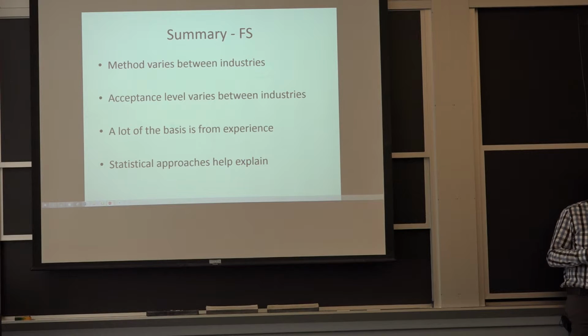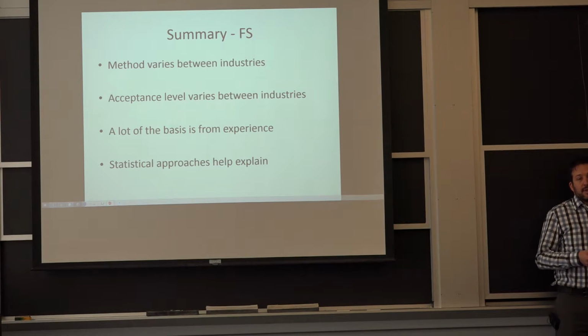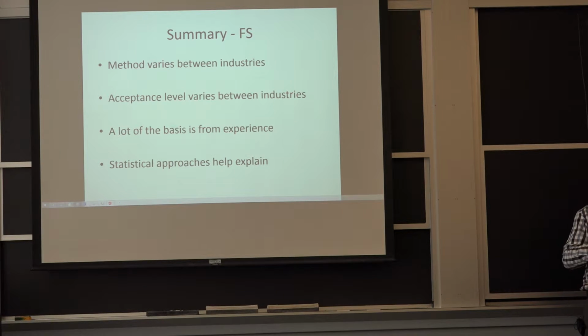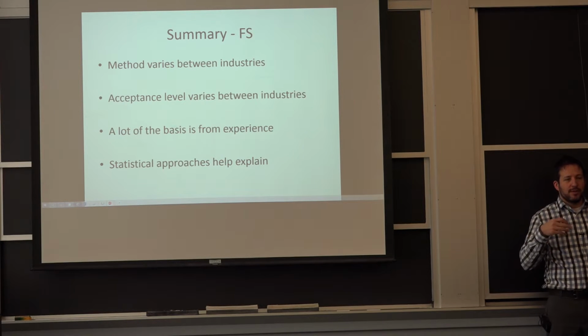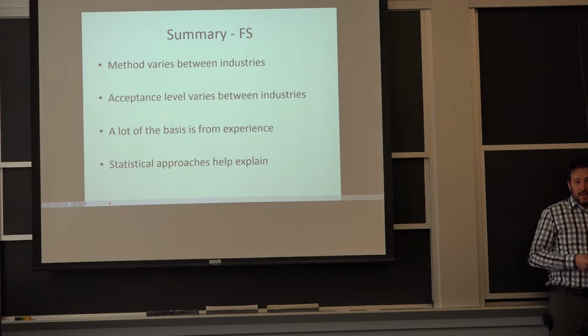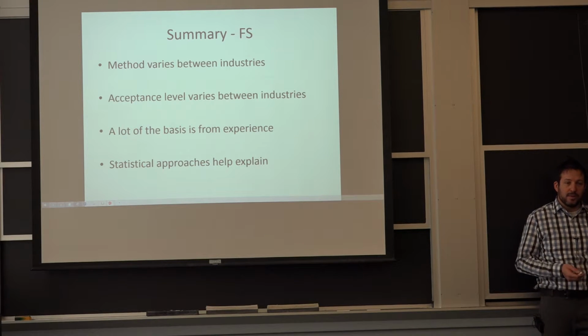I hope you gather that a lot of it is from experience. You have to think about all these extra parameters, temperature variation, rusting, that will ultimately happen. Maybe for you it's environmental degradation. If you have these expansion membranes, just cycling. If it's a stationary structure, but it does go through temperature variation, it will be essentially subjected to cyclic loads every season. Moisture can really be a problem.